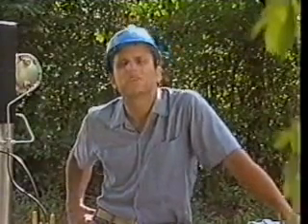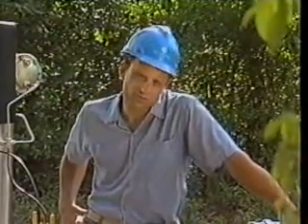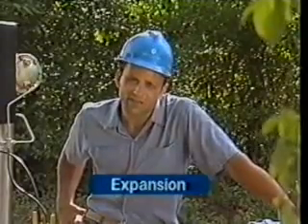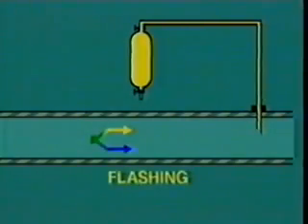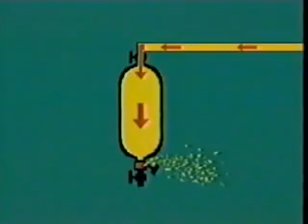When taking a gas or natural gas liquid sample, 3 critical areas must be controlled: pressure, expansion, and stratification. First, pressure must be controlled to collect a sample without allowing the composition to change. If back pressure is not maintained, the light ends might flash. Flashing occurs when the pressure changes, creating a 2-phase sample and altering the composition of the sample. If the pressure is allowed to rise, it can also rupture the relief valve, and part or all of the sample can be lost.